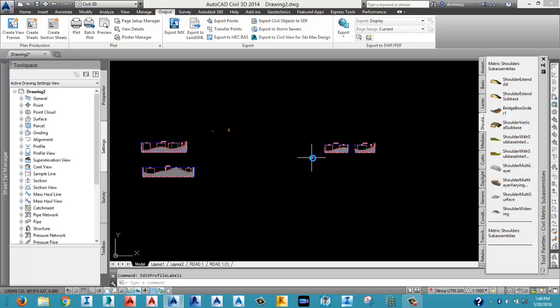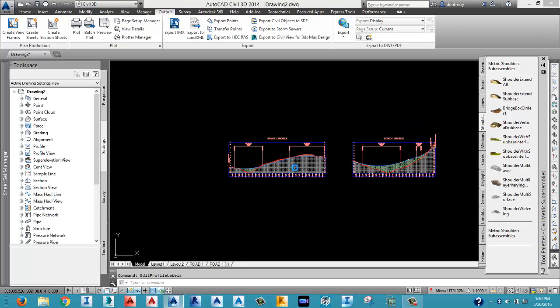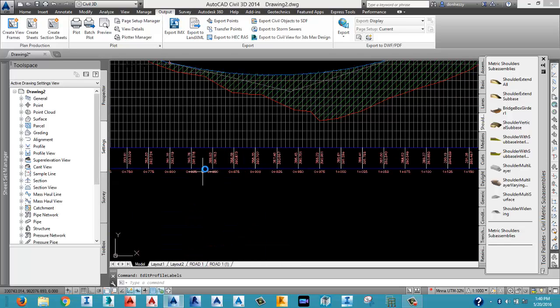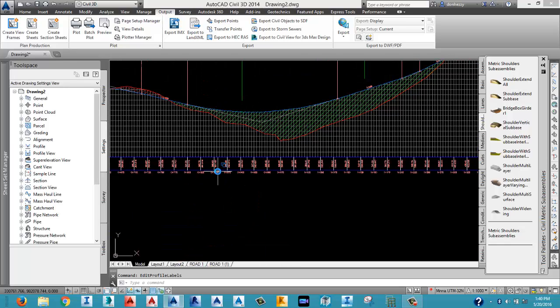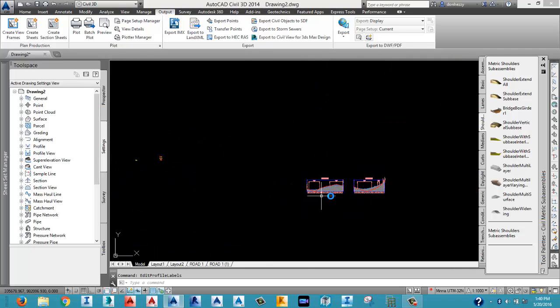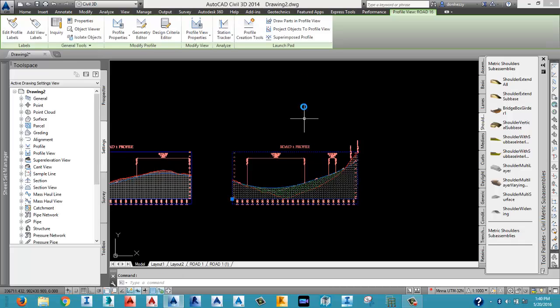The last one you do is just repeat the command for bringing up the intersection that we did. Remember? If you look at what you have there, your intersection falls between 850 and the last chain edge. So it can't be on the first one. Maybe it should be on the second or the third. Mine is on the second one, so I pick the second profile, and then I do the projection, like project to profile view.